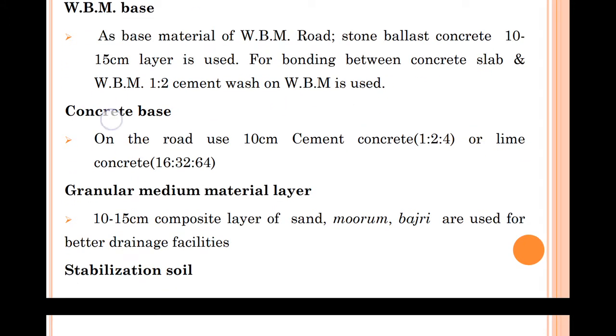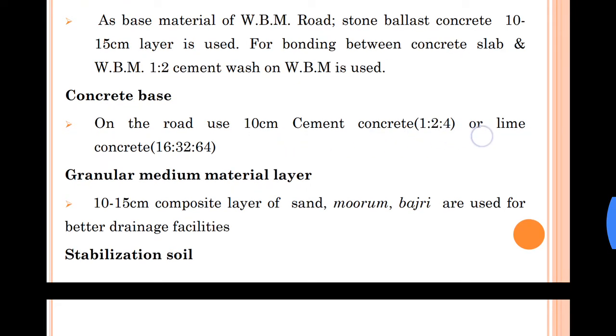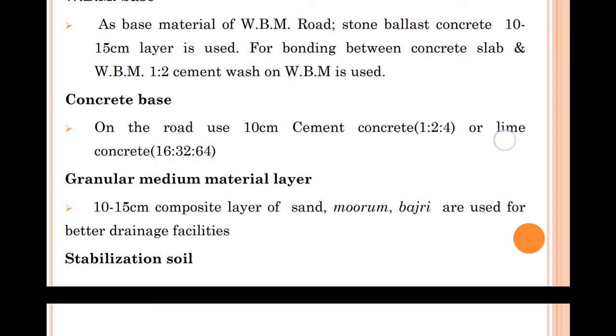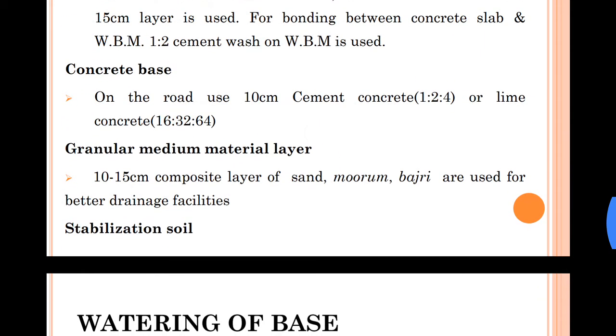And if you are using a concrete base on the road, use 10 centimeter cement concrete with ratio 1:2:4, or lime concrete with ratio 16:32:64.